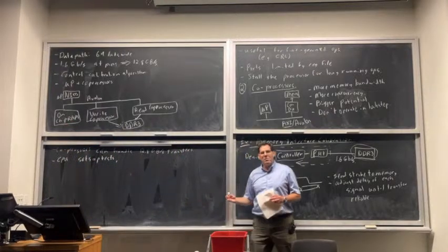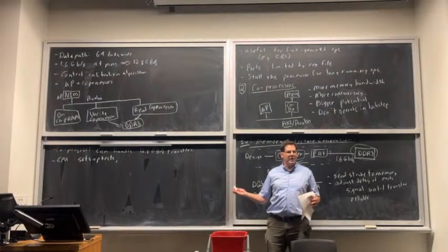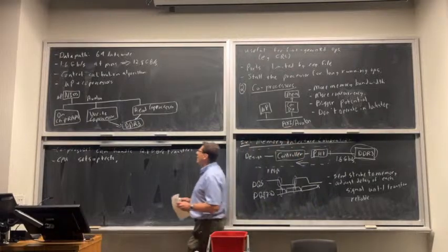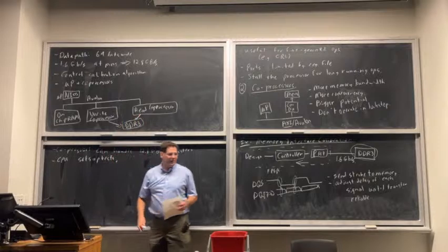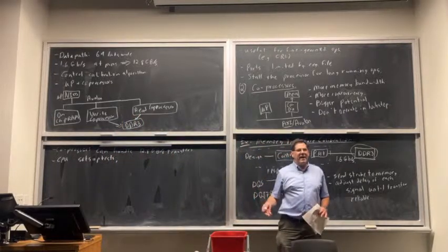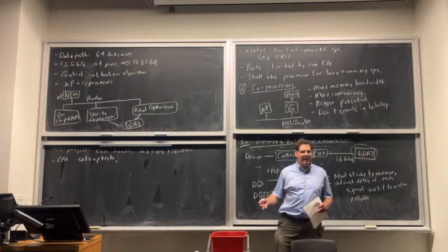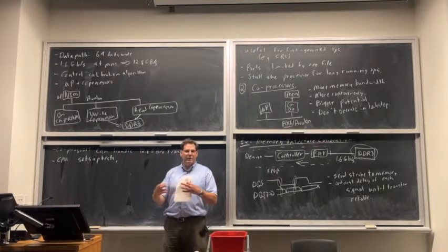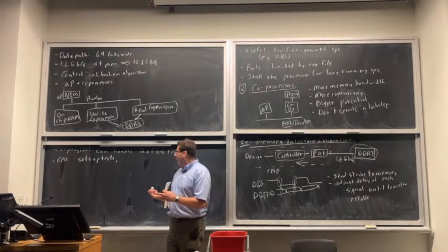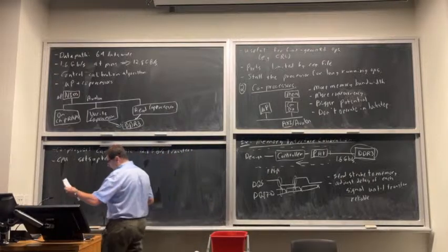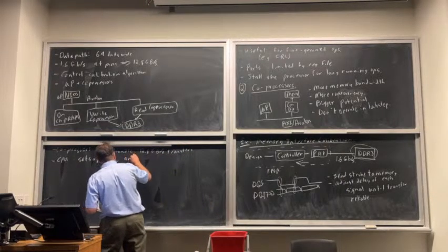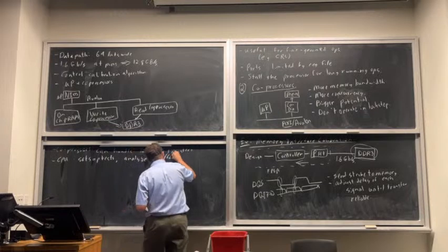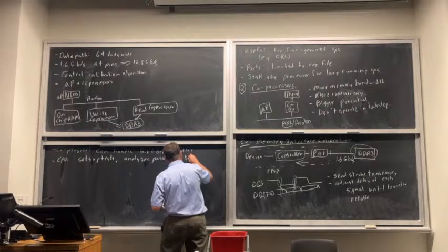So maybe it wrote a whole bunch of 0 values, and then when it looks at what was read back, it actually got some 1s. So it'll try something, right? It can then send commands to these read and write coprocessors to adjust the edge timing and try again. And it's going to try a lot of things, and analyze the results to try to figure out what to do next. Looking for how can I configure all of these edges and delays in order to get reliable communication. So it sets up tests, it analyzes pass-fail, and then it tries the next one, and so on.